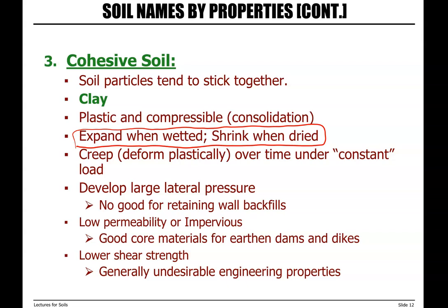As a result of these characteristics, there will be large lateral pressure. It's not a good material for retaining wall backfills. It has very low permeability, or is basically impervious, which makes it a good core material for earthen dams and dikes. It has low shear strength. So shear strength is important. And clay is a material that has low shear strength, which makes it undesirable for engineering properties.